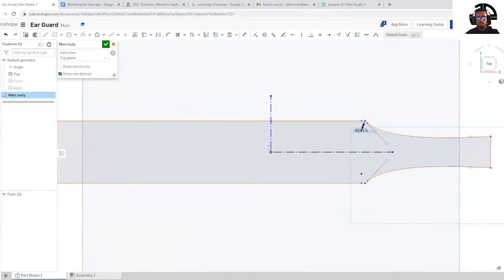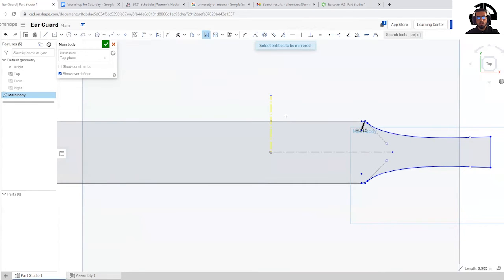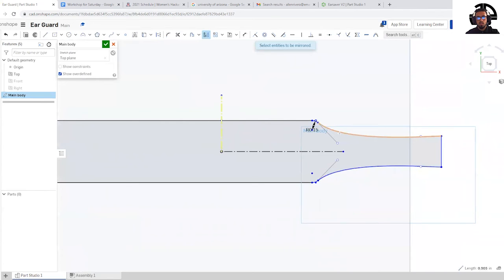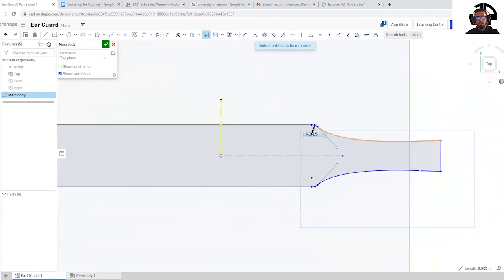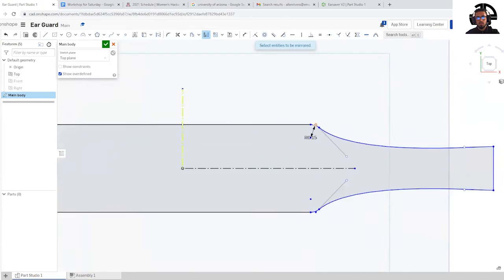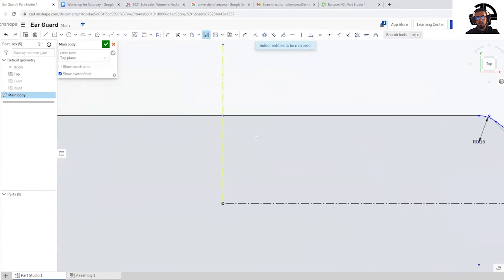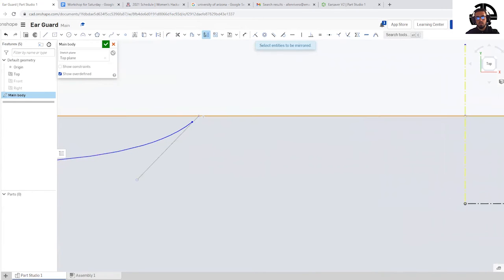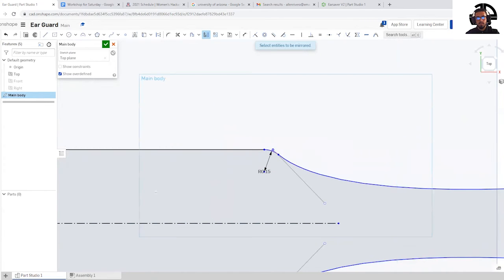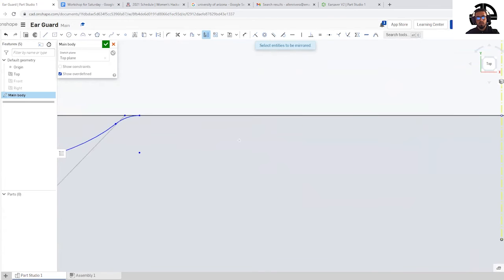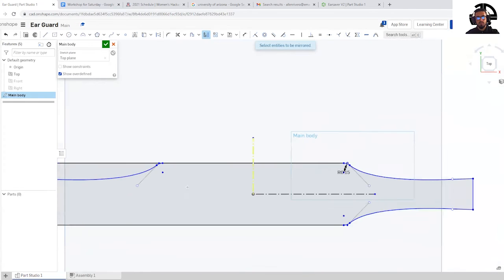So what I will be doing is, since I already made this mirror line, all I have to do is click the mirror function, click the mirror line, click this spline that we want to be reciprocated over here, and the curvature. Do not forget the curvature, or else these points do not connect, and I will show you that. You see how these points do not connect? It does not create a solid object, and we need a solid object. So click the little curvature that we made, and it recognizes it over here as well.